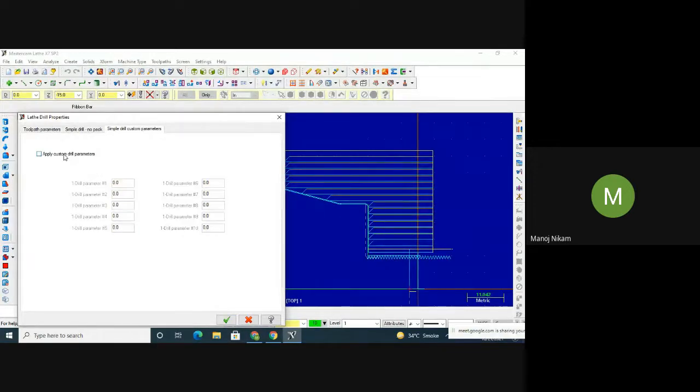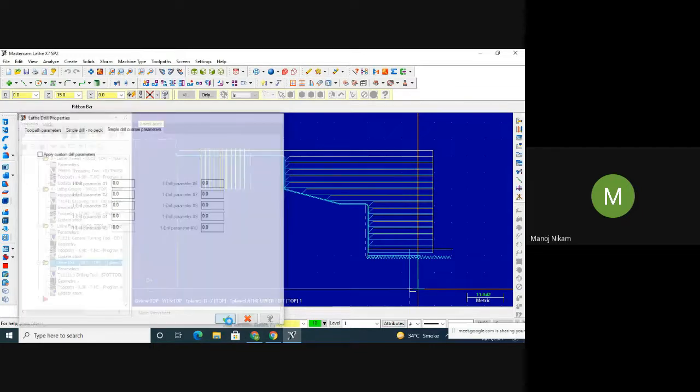I told you that drilling usually does not happen in a single pass; very often you have to go inside and then come back out. So that the chips which are coming at the time of drilling, we have to remove that excess material, otherwise it will get trapped between the workpiece and the tool, and it will decrease the life of the tool because it is going to damage the edges of the cutting tool. Ideally we usually keep multiple passes for that, but we are not doing that.